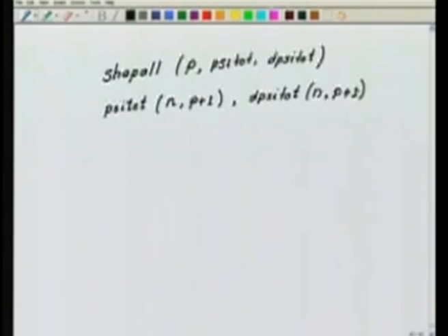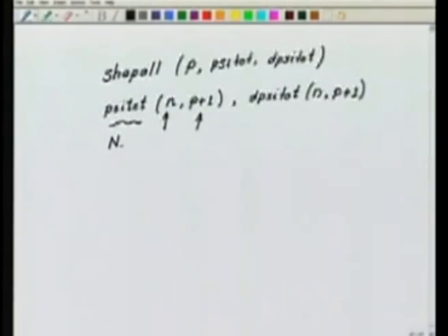What am I going to do here? For each integration point psi_I, I am going to load the values of all the shape functions of order p at this integration point. Similarly, here I am going to load at each integration point the values of the derivatives of the shape functions with respect to psi at this integration point. Okay.